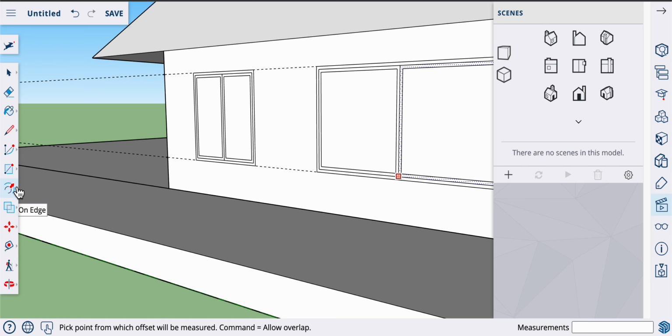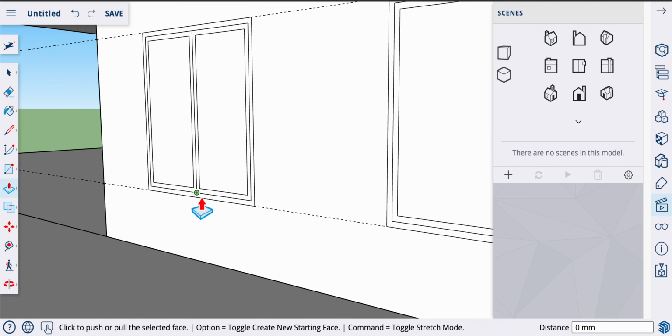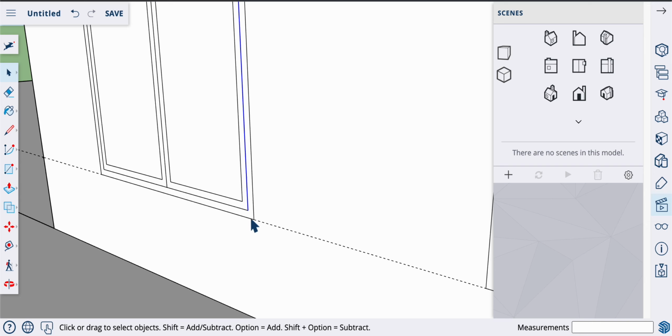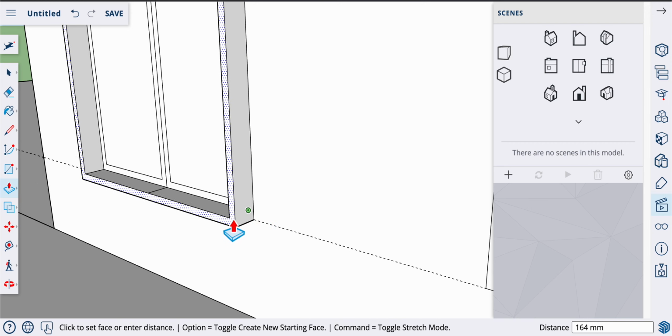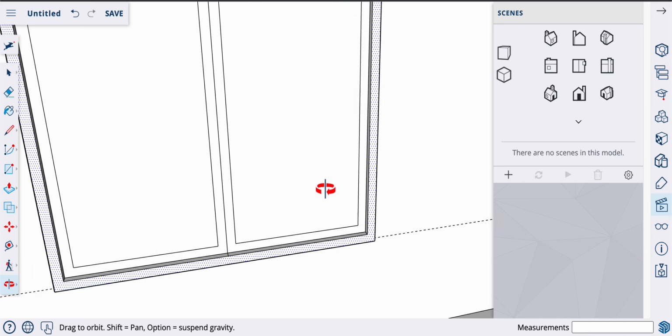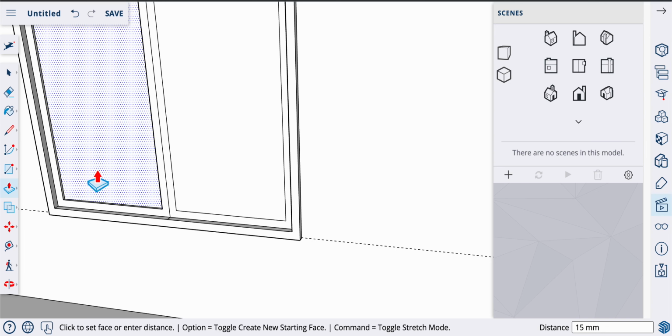I'll show you that maneuver. So I'll use my extrude and I'll zoom in plenty on my window, and what I'm going to do is select that surround. Sometimes you've got to zoom right in to make this work. There we go. Okay, so you can see I've selected that outside frame. It's now nice and dotted, so I could pull that out of the building a little bit. So just a touch, and then I've got these windows on the inside. I might grab those ones and push them just back in a little bit.